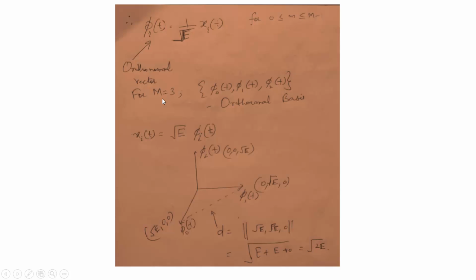If you see, when you select M equal to 3, you get 3 signal points, but it was not the case in the other schemes. What is capital N representing? Capital N is representing the number of basis functions. So when M equals 3, how many basis functions are required? 3 basis functions are required. But in the case of phase shift keying, if the value of capital M is, let's say, 8, how many basis functions are required? 2 basis functions are required to represent the constellation diagram in terms of the phase, right?